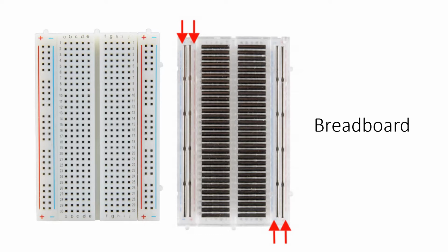Breadboard. So a breadboard is a way of creating circuitry. You can plug in the leads of your LEDs, diodes, resistors, and potentiometers into these small holes, and then also power the board by bringing power from a battery or some other source of power into these. Typically that's done into these vertical strips on the left or on the right.